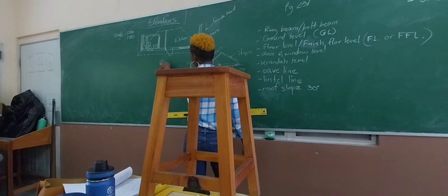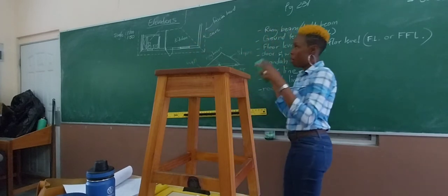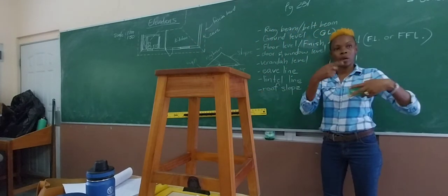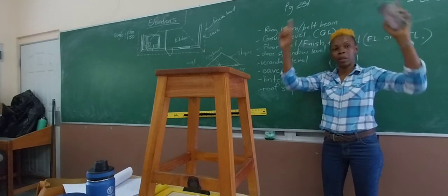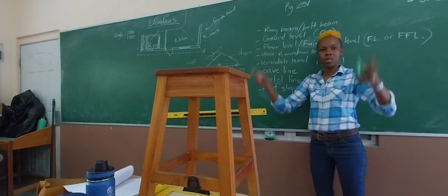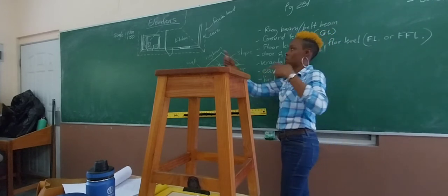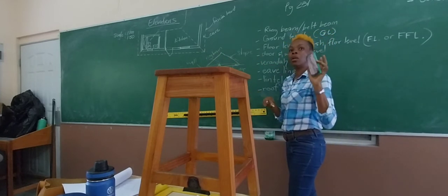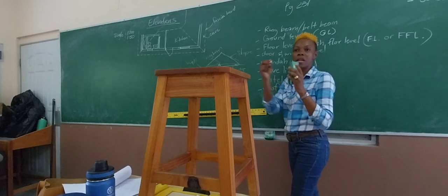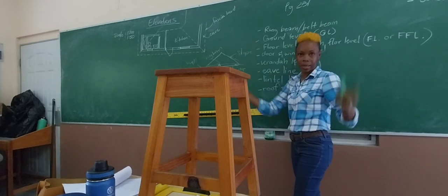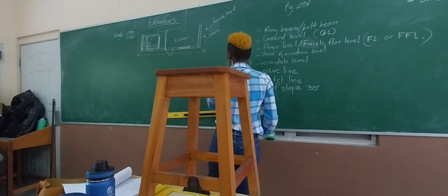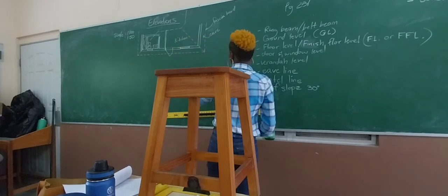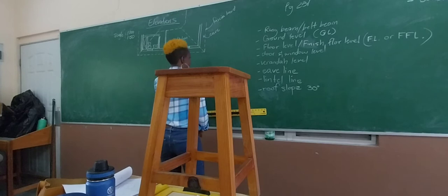So at the bottom of your drawing is where you're going to do your elevation. You have the floor plan at the top, and from there we're going to extend our lines to give us our width and so on. Now none of the widths are taken by measuring. We simply extend them, right? So let me take this up. You should have another drawing, plain paper at the bottom, so that we can start this elevation.